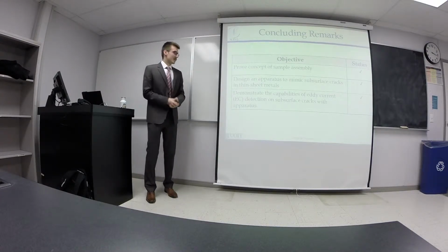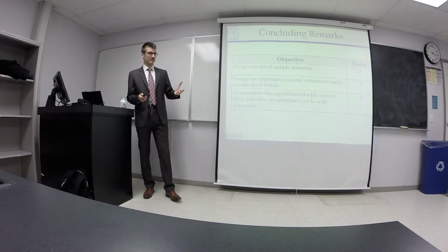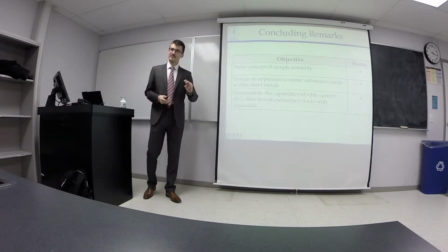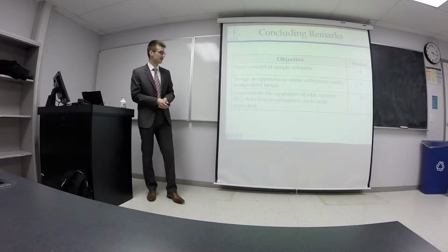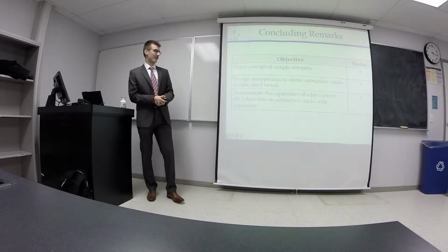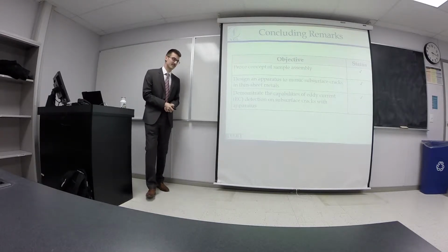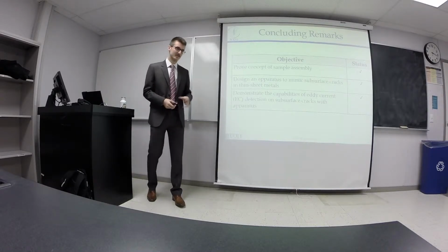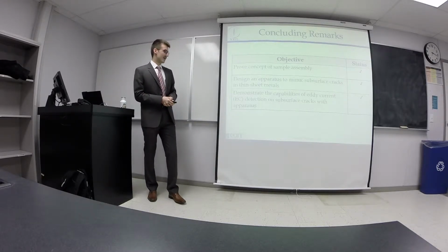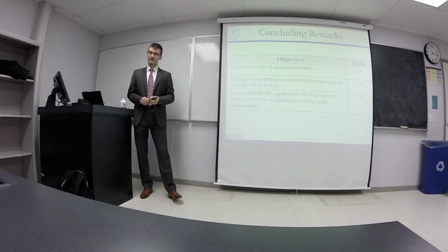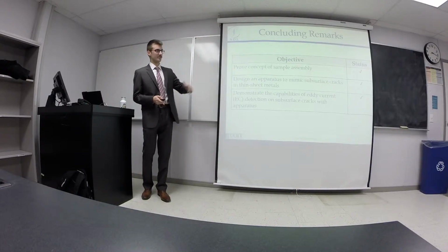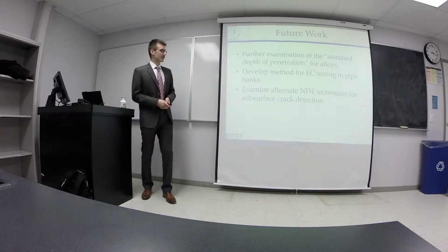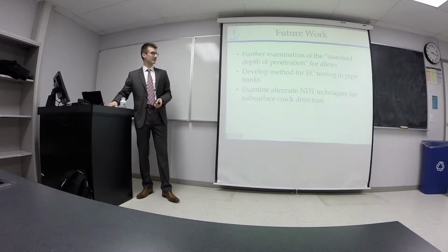So, concluding remarks: the proof of concept was demonstrated. I could show that you could successfully mimic subsurface cracks using the sandwich assembly we talked about. I did design an apparatus to mimic these subsurface cracks in these thin sheet metals. It's repeatable and it's fairly accurate. As well, I can demonstrate the capabilities of eddy current detection with this apparatus using the results I just showed. So, future work, I'd like to examine the standard depth of penetration for alloys.